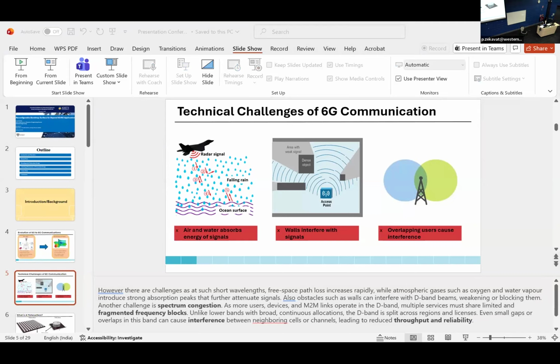this, I'll use a reconfigurable metasurface, as this further improves performance, controlling how the electromagnetic waves move through the environment. A metasurface is a two-dimensional array of atoms which each give a specific phase shift, collectively shaping the wave. And generalized sheet transition condition found that these phase shifts are like jumps caused by induced electric or magnetic polarizations from the meta atoms. And by engineering these polarizations, metasurfaces can achieve beam steering, focusing, filtering, and more.